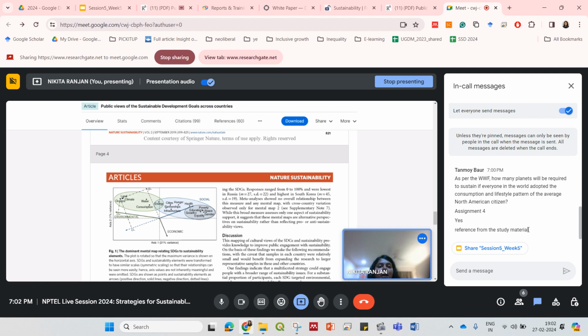Whatever we can do to mitigate the impact that we have already created, that is called mitigation. And adaptation is something which you do in order to be ready for the changes or the impacts that are going to occur due to climate change. So, forming resilience building techniques or making infrastructure that is resilient to the impact of climate change. So, maybe using nature based resources for stormwater management, maybe doing urban greening, either for carbon sequestration or for air purification or for reducing urban heat island effect.